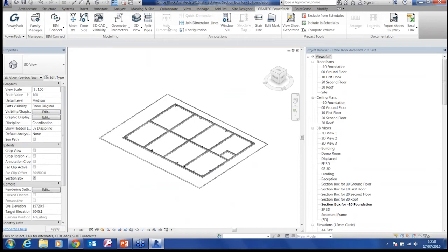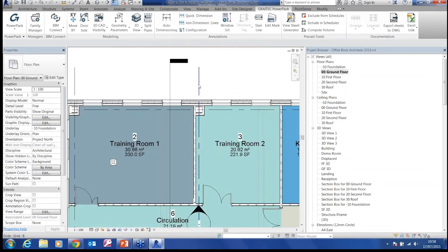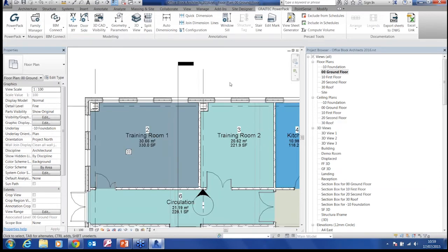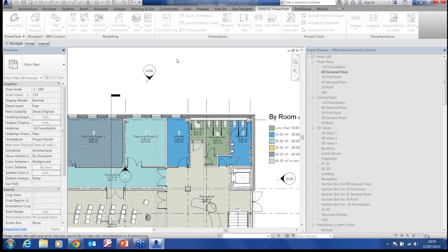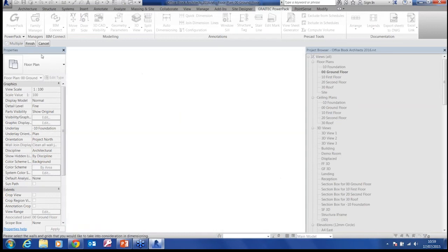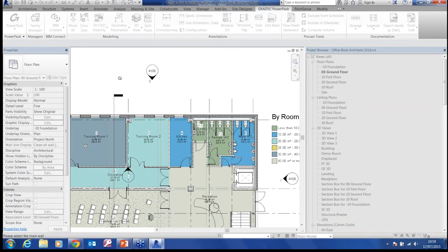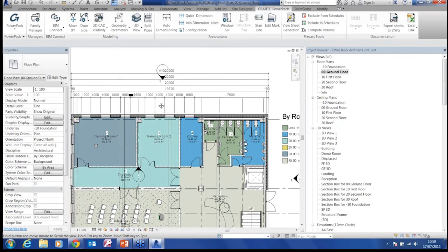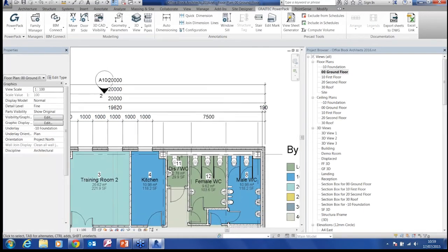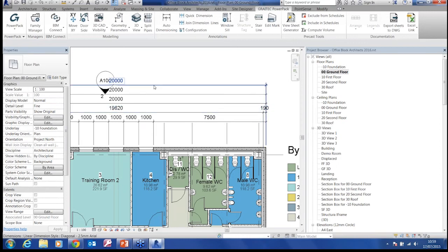other drawing. Okay, so auto dimensioning. I'm just going to go to the ground floor here, and we're going to start to have a look at some of the cool tools that are in here for dimensioning. So first thing I'm going to do is come into this view. Auto dimensioning, and it says please select the wall and the grid. So there's my wall. Okay, let's just redock that. Hit finish. And specify the wall. Specify the start where I actually want it to go. And it's basically now auto dimensioned the whole of that wall with all the other intersections as well.